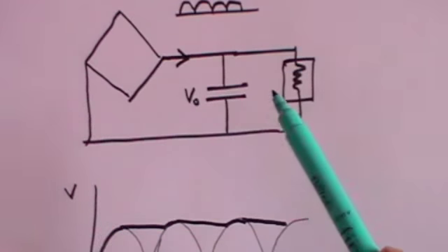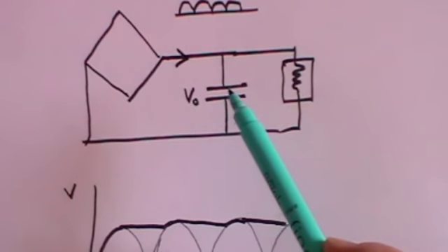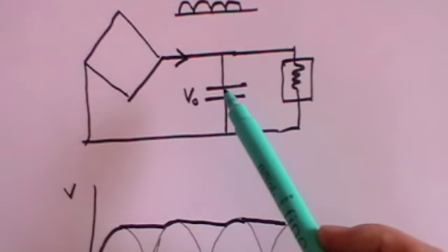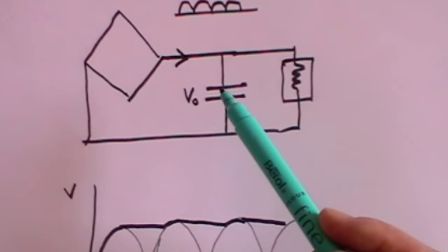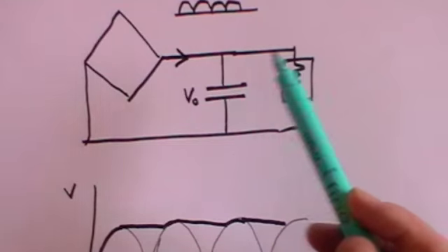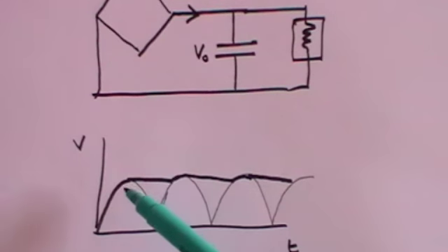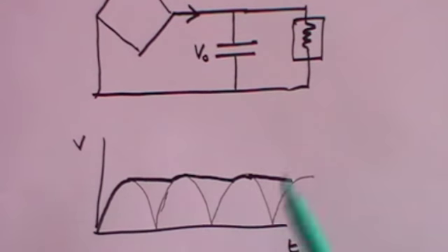So what you need to do is to put a large capacitor, which will charge up to a maximum voltage of V0, but it will slowly discharge, and that means that as this alternating current varies, the capacitor acts, as it were, as a DC supplier. It effectively becomes a battery supplying a DC supply whilst the current would go down and back up again. It can smooth out that voltage and thus provide a pretty much constant voltage for the computer.